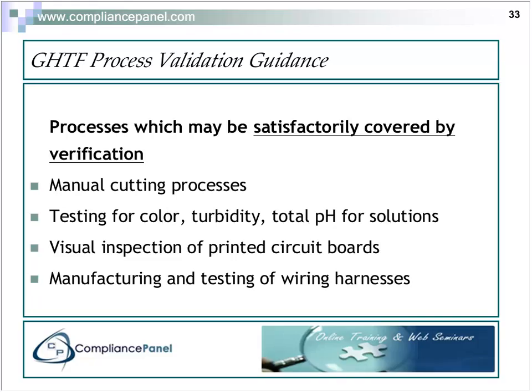Okay, for those printed circuit boards, there are certain workmanship standards that you can measure against for certification or for verification, but again, the FDA does have some very specific leanings towards, hey, we want those soldering processes to be validated. Now, I think here we're talking about visual inspection of the copper-plated board before the components are installed and soldered.